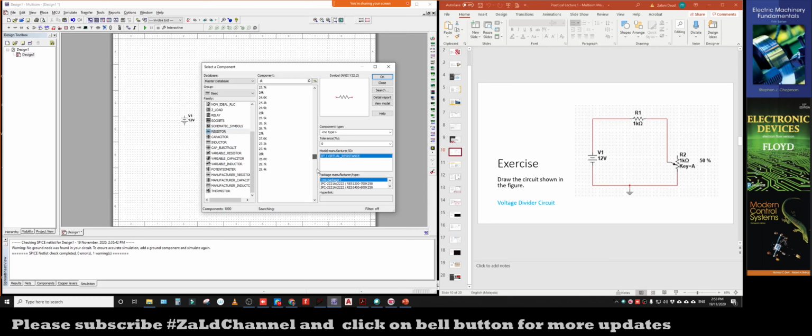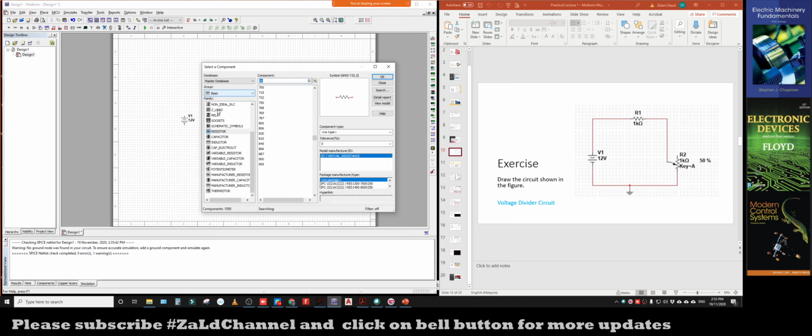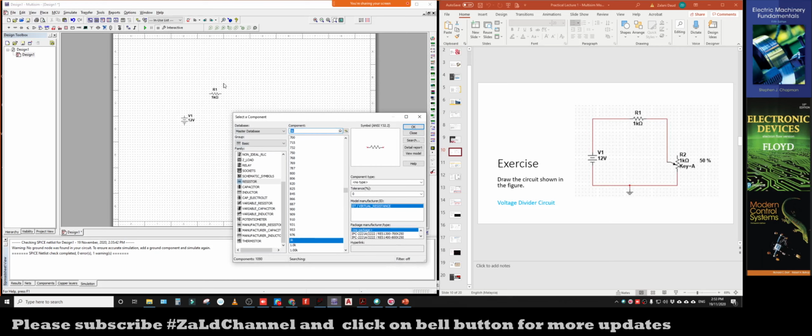Okay, so for this resistor, we want to place a 1 kilo ohm resistor. So just find the 1 kilo ohm resistor in the list, then click OK. Then you place the resistor in an appropriate place, which is maybe around here. Okay, so I have already put the source and resistor, which is the 12 volt source, the same as this one, and also the 1 kilo ohm resistor.